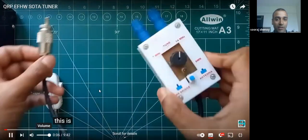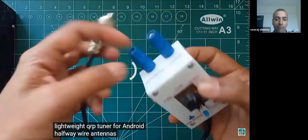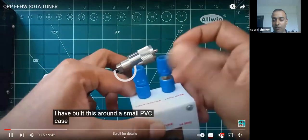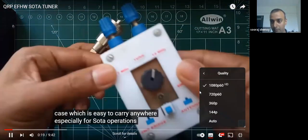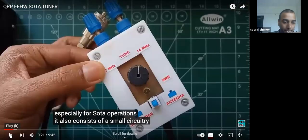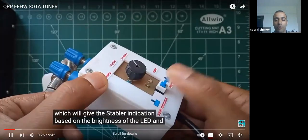This is a short demonstration on a lightweight QRP tuner for end-fed half-wave wire antennas. I have built this around a small PVC case which is easy to carry anywhere, especially for SOTA operations. It also consists of a small circuitry which will give the SWR indication based on the brightness of the LED, and it can be tunable from 80 to 17 meters.